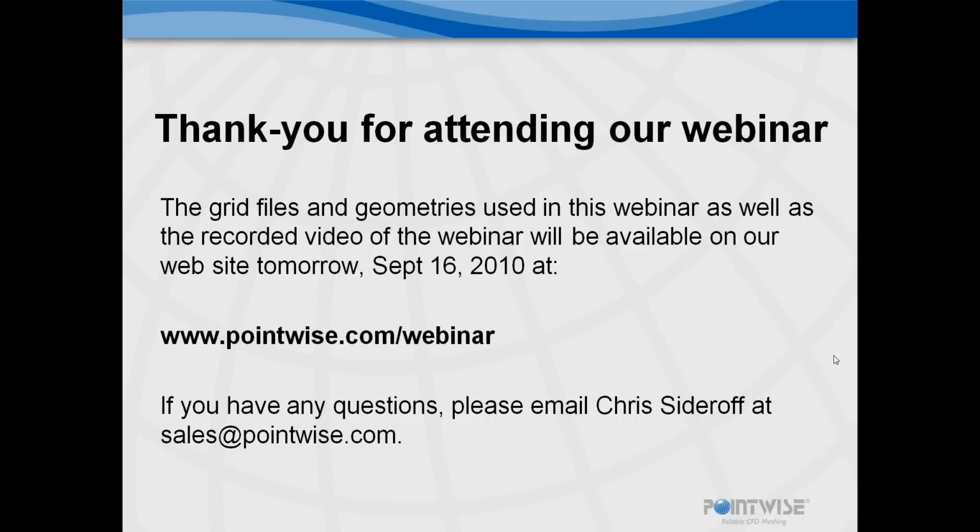There are some techniques that you can do. You can project onto the surface locally, or you can do a local approximation of those surfaces so that you're capturing the design intent without necessarily projecting onto the CAD that is so dirty. So there are a couple of different techniques, but those are the methods that we would use when we're dealing with dirty CAD, that is where the imperfections are on the order of the grid scale.